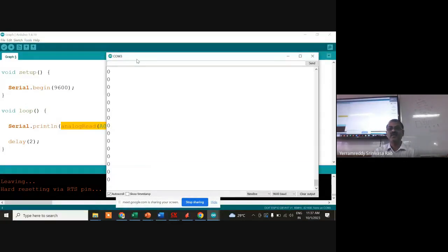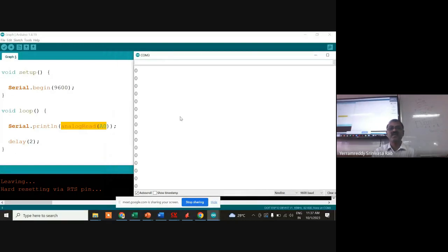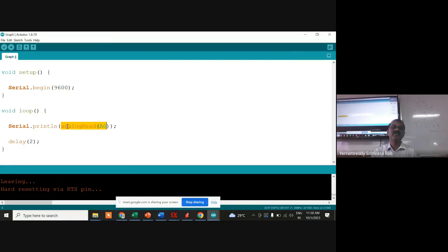If you see serial monitor, अभी right now it is displaying some number 00. If I touch the pin, देखो अभी number कैसा change हो रहा है. If I touch that analog pin, okay, change हो रहा है कि नहीं? 2 to the power of ये 14 है, इसलिए 4096 तक जाता है. So understood how to display the data on computer monitor by using serial print line.